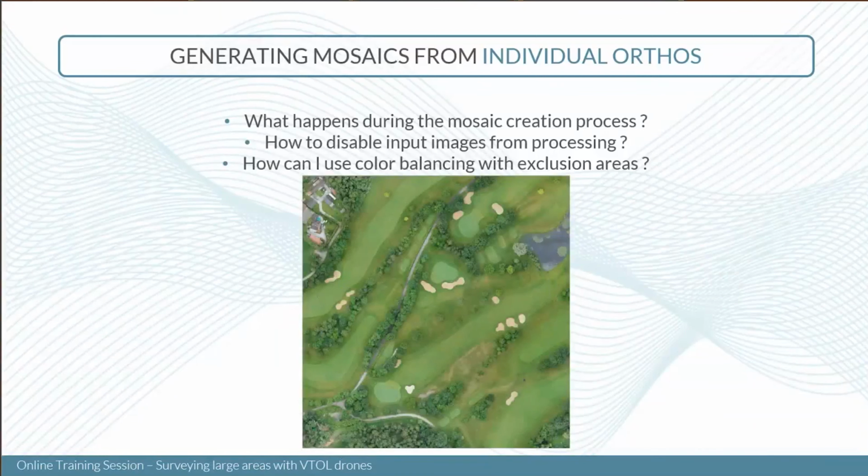So the first step is to generate the ortho photos, as I was mentioning. By generating the ortho photos, you'll be able to ortho rectify either on your surface model or on your terrain model, depending on your need. So you'll either have a true ortho, which is an ortho over the surface model, or just a classic DTM ortho over the DTM. And then, once the ortho has been generated, you'll be able to create your mosaic out of this.